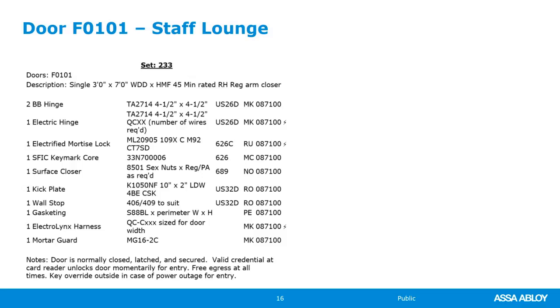I've had hospitals before where, in new construction, there were electric strikes and the supplier didn't notice the templating. They ordered the frames with the electric strike in one location, then they had to try to modify with face plates. It's just an extra layer that you don't really need. You're gonna have a mortise lock anyway. You're gonna hang the door anyway. It's brand new construction. Why not do the through wire?